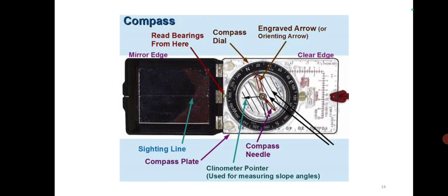The division on the circle from 0 to 360 degrees goes anti-clockwise, so east and west are opposite from a normal compass. It is marked this way so that you can calculate the azimuth of the strike directly from the position of the north.